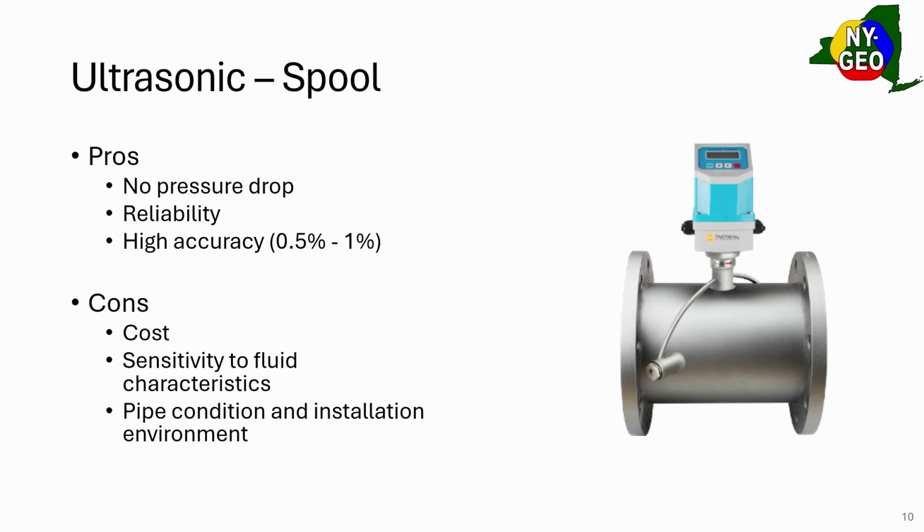So what are those sensors? Flow, you know, all the ones you mentioned. So that's a BTU meter. Sure, yeah, but it's just a combination. You can build your own for sure, right? But it's just a combination of delta T and flow.